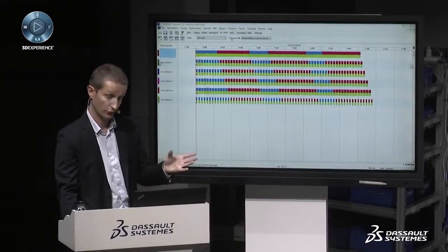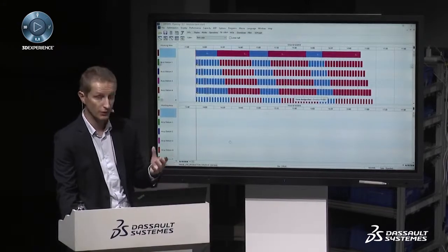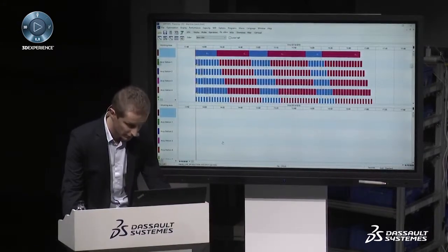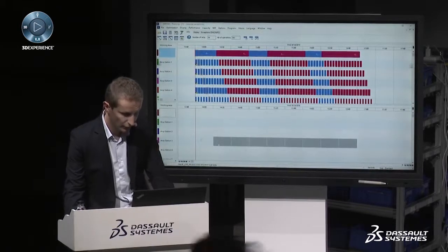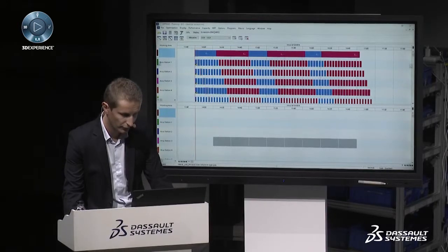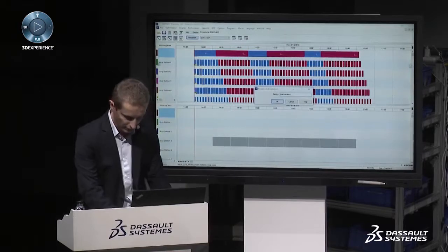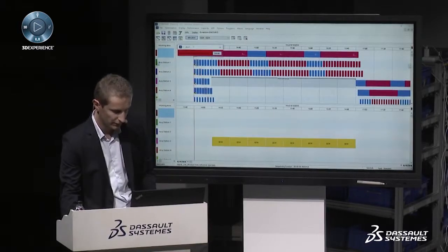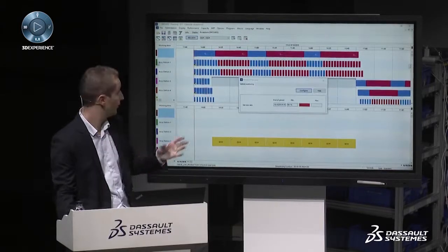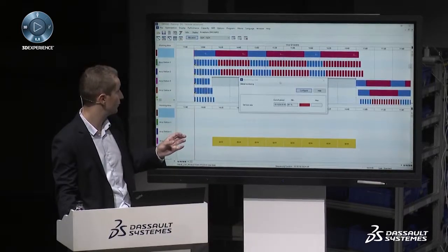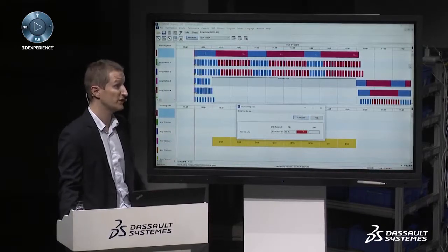Yeah, but we have to plan some maintenance. So good. But let's quickly insert our mandatory and unplanned maintenance on the press. I will just close station 3 from 2 to 5 for 3 hours. I will put a maintenance designation here and see what the impact is. Okay, so here I have a dynamic and automatic alert warning me that with this new constraint, the maintenance taken into account, the service rate, so the percentage of work orders on time, will drop down to 56%.